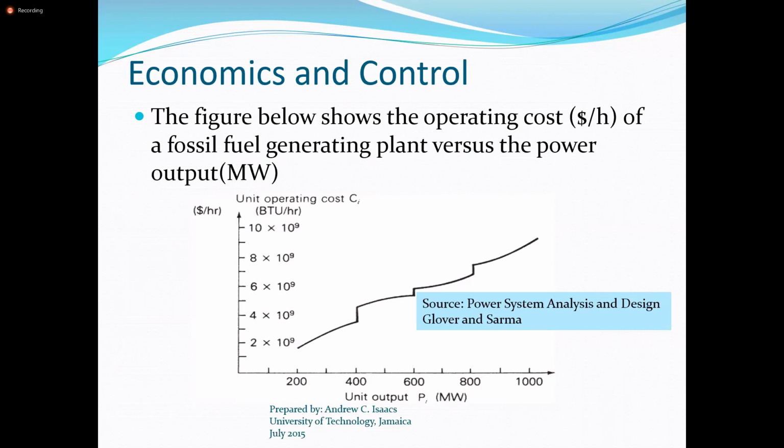Delta and V will both change. However, the change in V is going to be more significant than the change in delta. When you do the reverse in holding Q and varying P, you're going to see a greater change in delta rather than V.